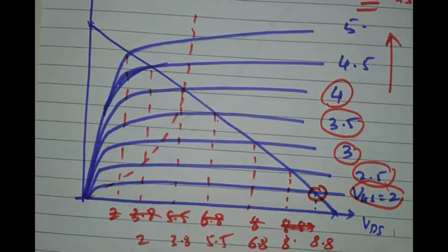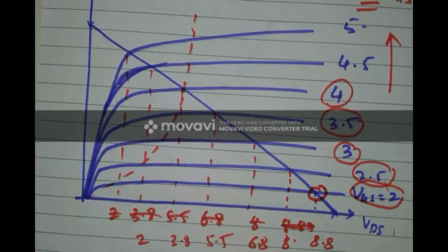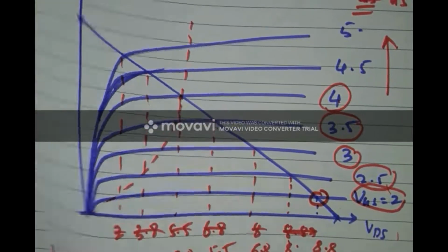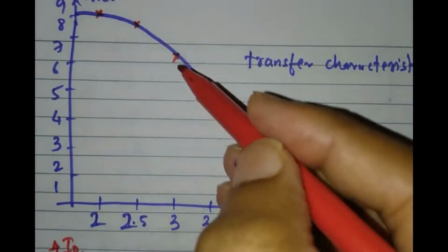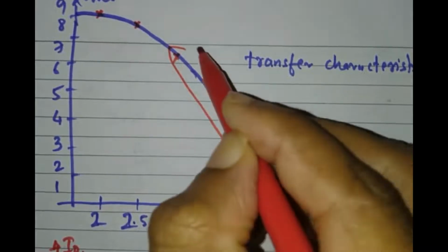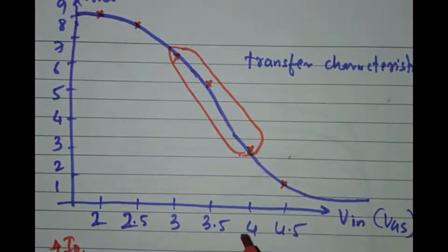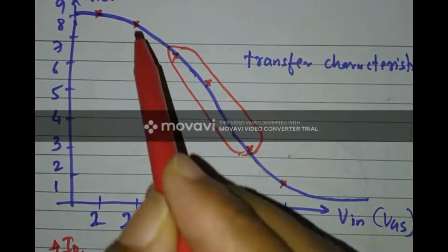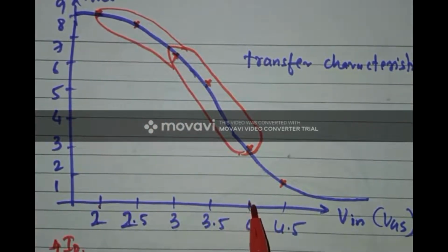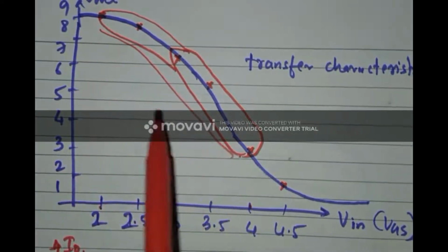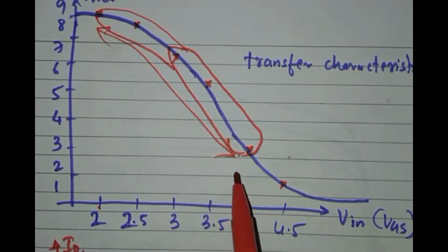And this makes the foundation for amplification that we are going to perform by pushing the MOSFET in the saturation region. So the same thing can be seen over here, the graph which we have done. As you can see here, these are a few points where, like for example, I told the MOSFET has to be more than 2 volt, less than 4 volt. So this is the region where I can say that the MOSFET will be in the saturation